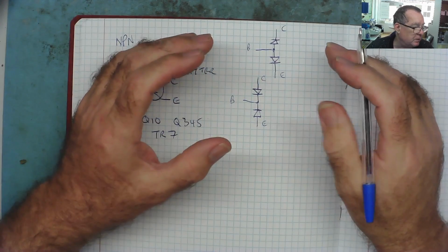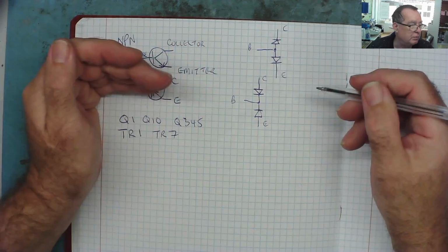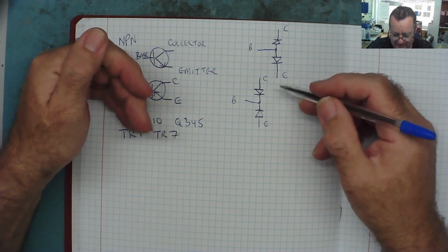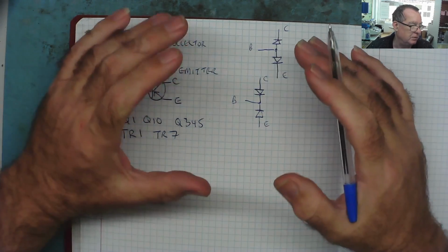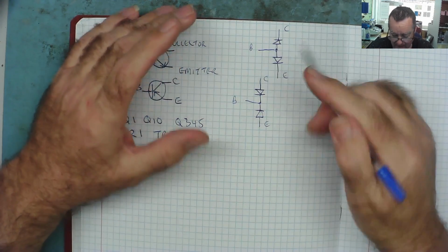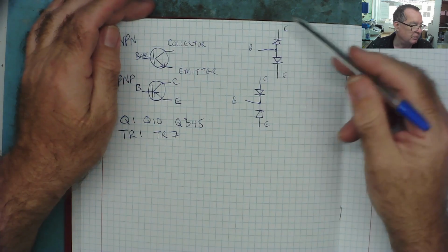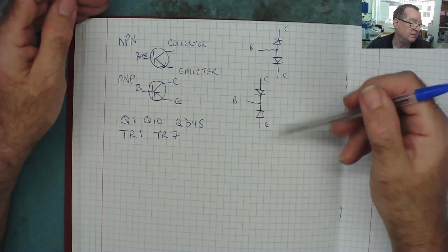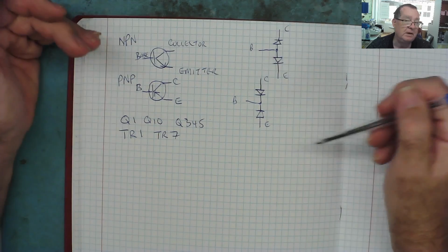Now, just because a transistor looks like 2 diodes doesn't mean that you can make a transistor out of two diodes. You cannot actually make a transistor that way. But this is electrically how it looks to your meter. Now we know this, let's have a look at least a couple of transistors and see what we can see.